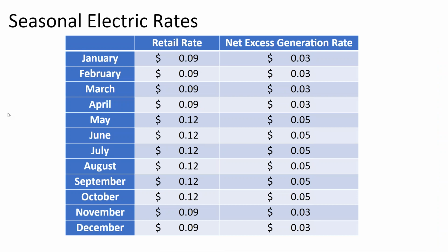Let me go to some questions. What is the average square foot weight of the panels, track, wiring, electronics, and anchors on the rooftop? It's about 3 pounds a square foot. And we'll show you some racking software probably tomorrow that will calculate that for you.